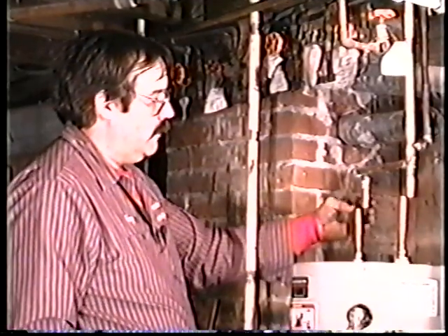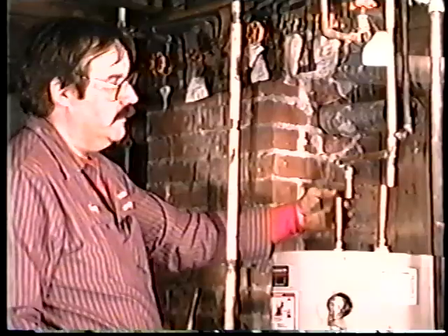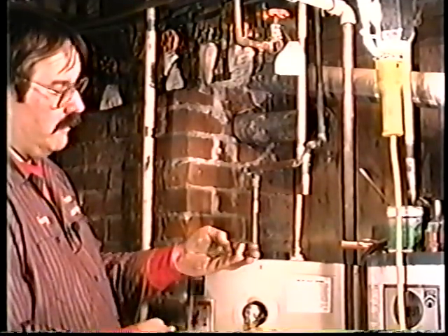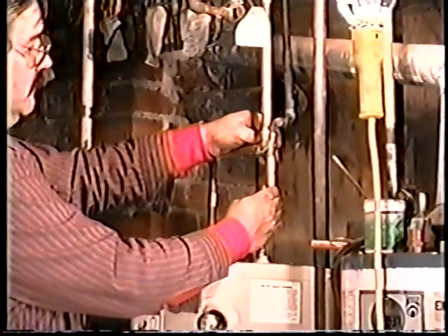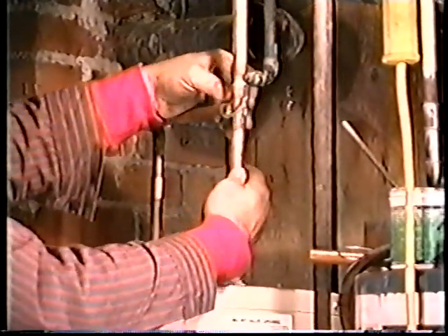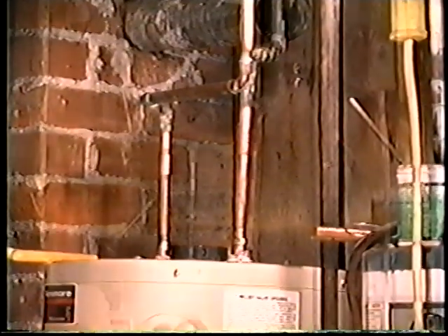Then we can proceed to make the last connections for the hot and cold water, which we'll use with soldered couplings that'll connect these lines together, and that'll be the water connections. So we're going to join these two pipes together to the water heater now. We use what's called a coupling. It's a very common solder fitting. That would slide up on the piping, and I just bring the piping over, slide it down, and now those two couplings can be soldered.